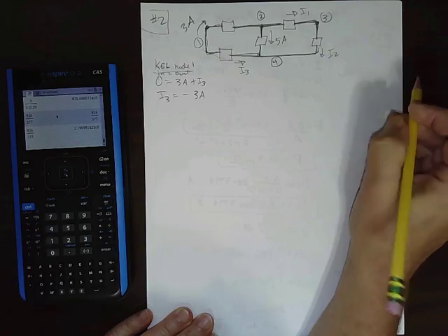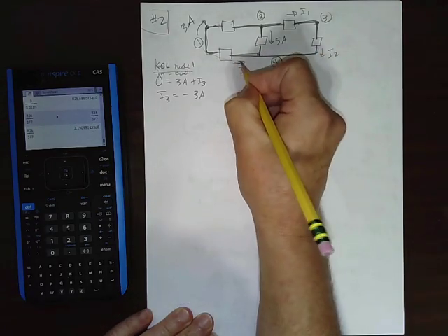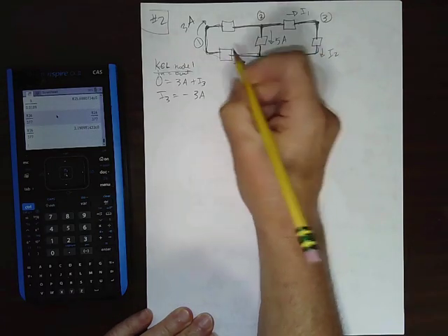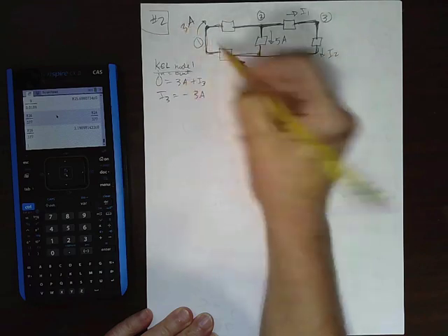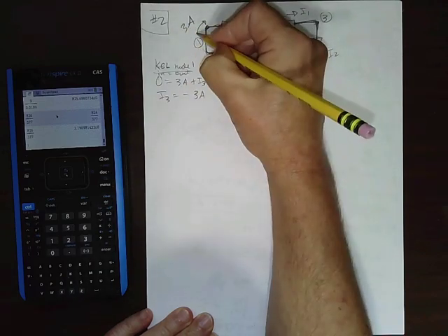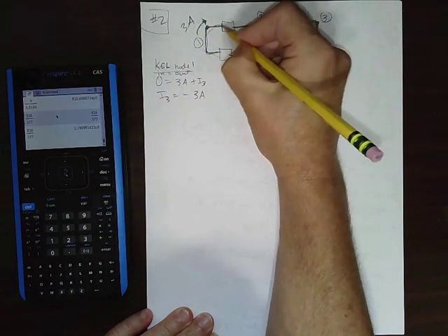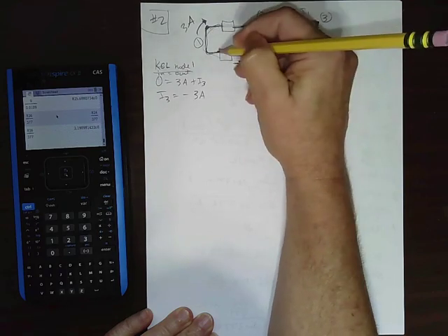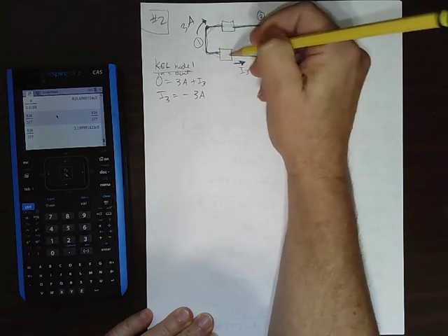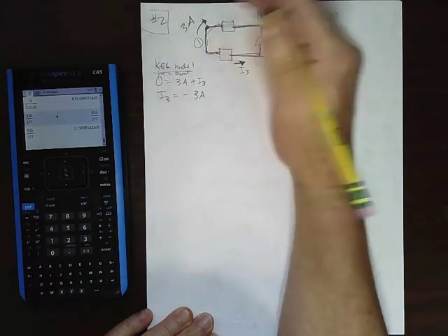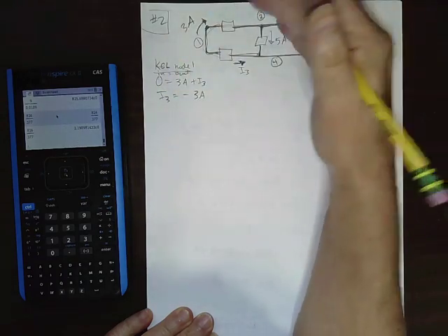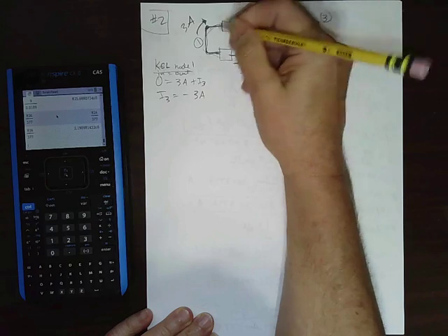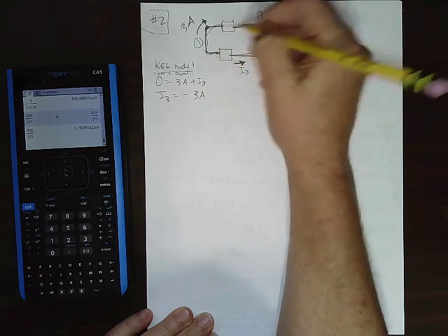Hopefully you will get to where you can just look at a picture and say, okay, I3 and 3 amps, they're the same thing, except they're going the opposite direction. Current flows through things. Whatever goes in one side of an element goes out. Current doesn't get used up by elements. Charge does not build up inside. In transient cases, in a capacitor, yes, but we're talking general steady state stuff. Current doesn't build up, charge doesn't build up, so what goes in comes out.